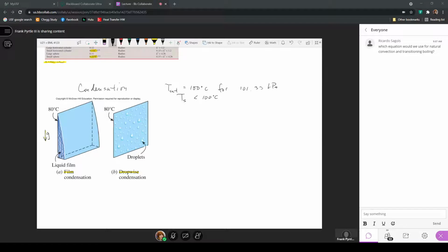So here, if I have a hydrophobic surface, the weight of the droplet that is required to overcome the surface tension forces is very little, and thus the droplets can be very small and still just slide right off the surface because the surface tension is so low. But if you've ever applied Rain-X to your windshield or some other hydrophobic material, you know it has to be reapplied.